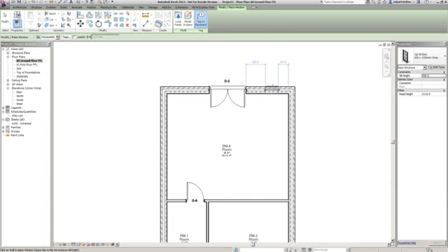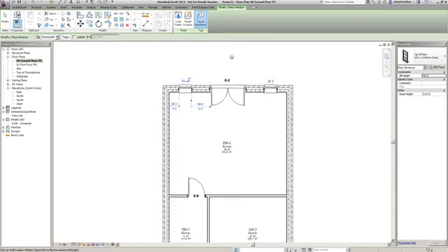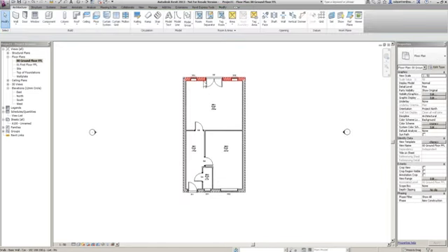And then in the rear elevation, let's put a couple of deep windows in here. About 500 from there. Window 3 and window 4 just there. Like that. There we go. Nice and simple. We've got the start of our ground floor going in there really, really quick.